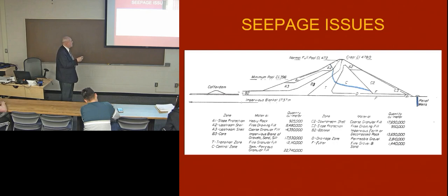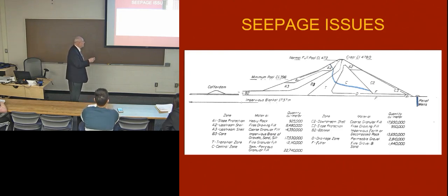But you'll notice how crazy it kind of goes, but the reason is it's passing from one kind of material to another. Another feature of flow on this diagram is over at far right side here. Near the downstream toe are relief wells. Relief wells, the phreatic line, all have to do with flow nets.